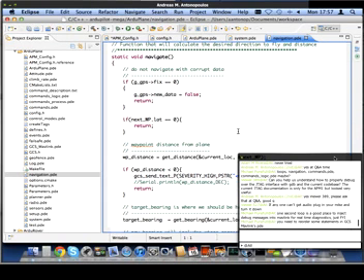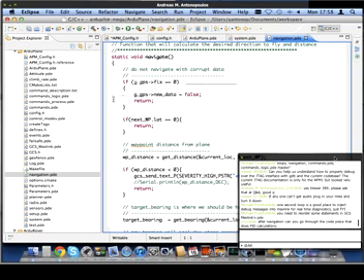Okay, so navigation in ArduPlane is based on waypoints. As I mentioned earlier, you can upload a set of waypoints to the APM, which is then stored in the EEPROM, and those waypoints contain a latitude and longitude and an altitude, usually as a relative altitude, using the barometer, relative to your ground altitude when you initially turn the APM on. And what the navigation code is designed to do, its input is your GPS location and your orientation, your attitude, the roll and pitch and yaw, so you know what heading you're on.